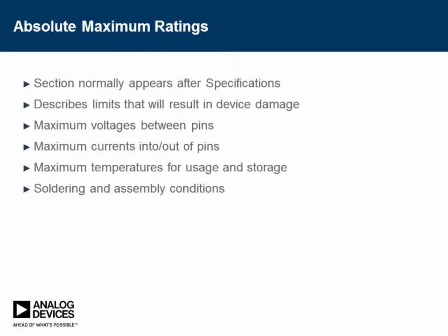Maximum voltages between the pins, maximum power supplies, the amount of current that can be tolerated in and out of pins, maximum temperatures for usage and storage, and then the soldering conditions. So, all of these things matter.